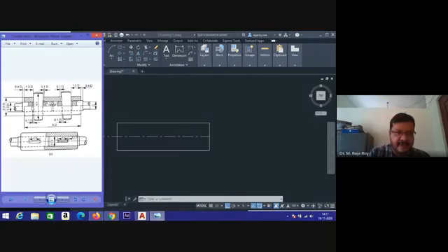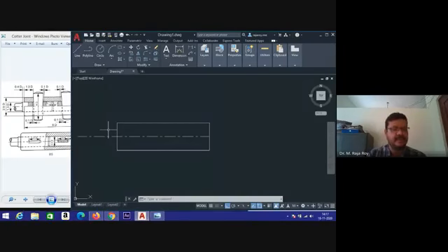So the center line part I have completed. Now I want to move from here 0.4D distance. After that I want to move up to here. That means 2.5D by 2 distance I want to move. So the 0.4D distance is 0.4 into 30. That is 12. Here this small distance is 12. Here to here you can take 12 distance.